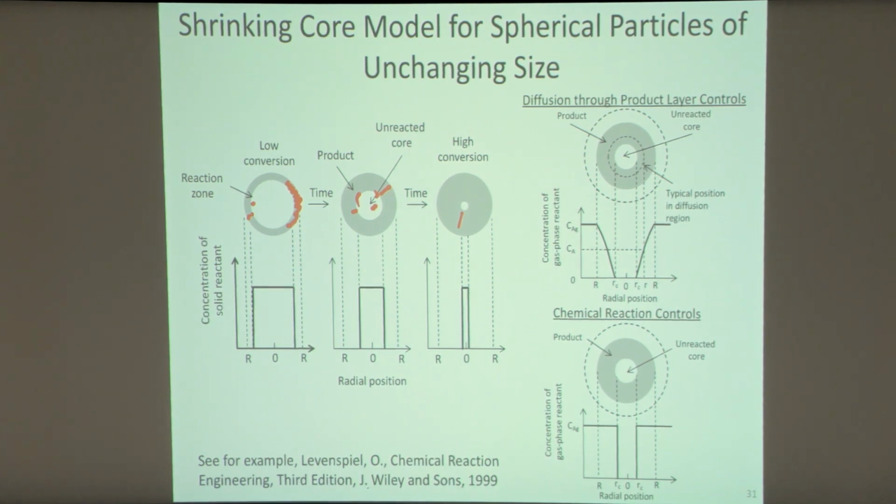Because now, if I've got to diffuse the oxidizer or the fuel across that thick condensed phase oxide layer, can that diffusion process start limiting the burning process instead of the kinetic process again? Or is it kinetically limited here at this interface? So now I've got another set of conditions to look at where the combustion process is being controlled. And that's what a shrinking core model does. So you can see on the right here,